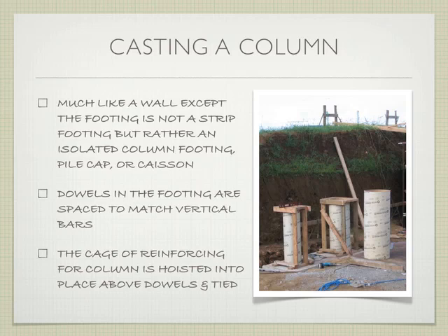These are becoming far more common because they stay in place and because they provide the insulation. The only gripe I would personally have about it is that you may be stuck pouring it in two lifts, which can cause a cold joint, which could be problematic in an earthquake zone. It would be up to the engineer. But I would say these are becoming more and more popular, especially in places where insulation is of value, so back east and that sort of thing.